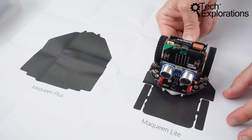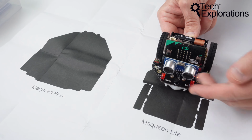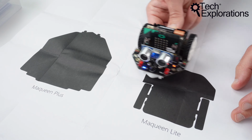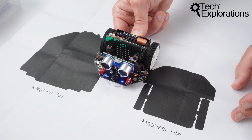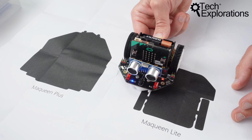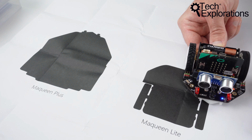Calibration is complete. And now the calibration worked, because when the two sensors are over the black area, both of them are off, so the blue LEDs are off. When you go to a lightly colored area, so the white area, they're on, and you can have one on and one off, and then the other one on and the other off.